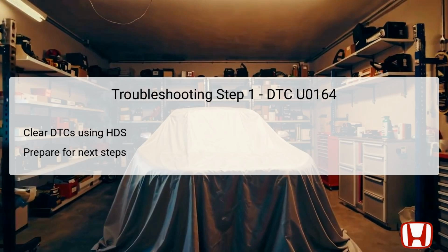After this waiting period, the technician should check for any DTCs with the HDS to determine if U0164 is still present.